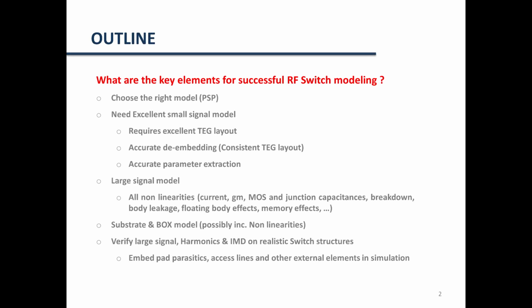First, we need to correctly choose the right model for that purpose. Next, we need an excellent small signal model. I will then talk about the large signal modeling and what is required to obtain such an accurate large signal model. Then I will give a few words about substrate and BOX modeling, possibly including nonlinearities. And then I will detail the verification of the large signals and the harmonics and IMD under realistic switch structures.